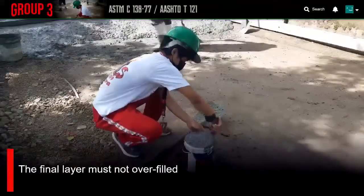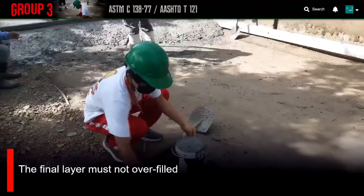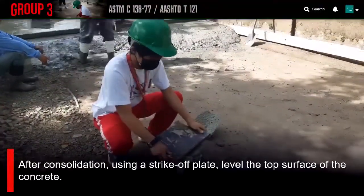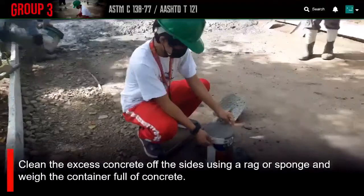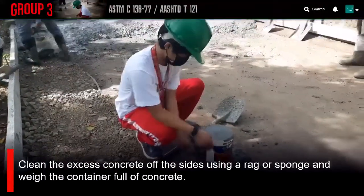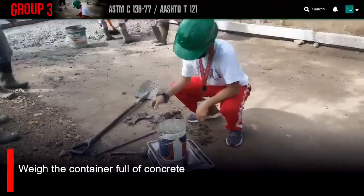The final layer must not be overfilled. Finally, strike off the top surface with the plate. Clean the excess concrete off the sides of the container and then weigh the container full of concrete.